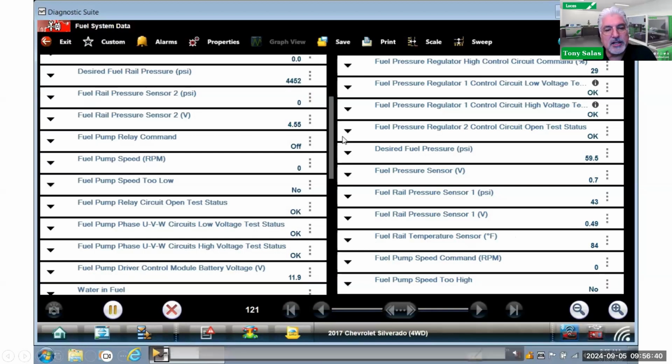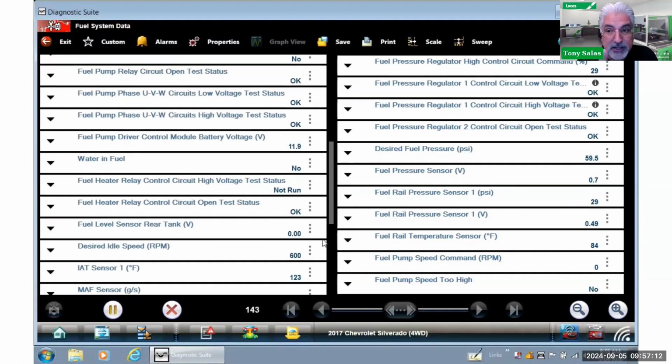So nice. Now, if you haven't taken an L5P class or haven't seen our L5P presentation that we've done here with Lucas, obviously go to the Lucas YouTube page and take a look at it. There's a whole bunch of them we've done. And in this case, you're going to notice you can actually read your fuel pressure. In other words, what is your lift pump pressure there? And in this case, you can read desired, actual, and signal voltage for the rail pressure sensors. And you can also look at lift pump pressure as well. So there you go. You can do a lot of diagnostics by looking at your PID data, provided you've done your basics, right?